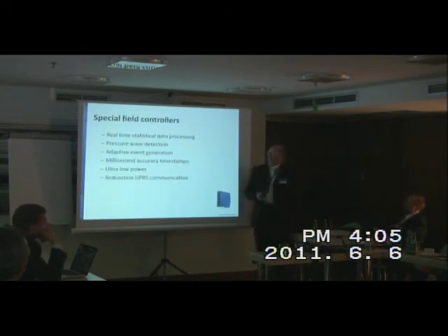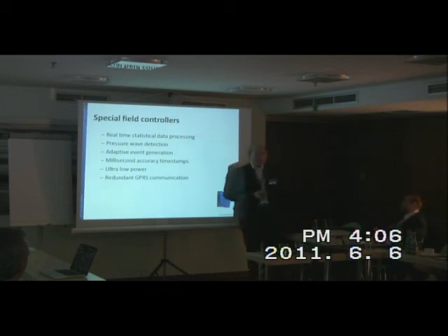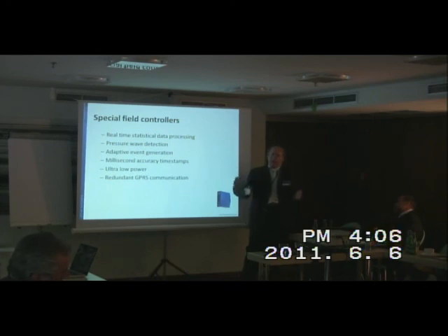We developed our special field controllers in order to process data in the field, to communicate this data by GPS communication to a central server, and in the field to synchronize the timestamp, because the timestamp is very important for us. For each pressure value, we put the timestamp together with it, and then we process this value in order to detect the leak events.